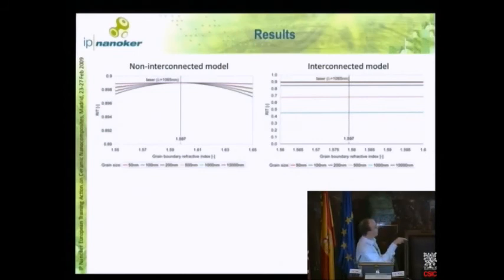So for different grain sizes, here we have the 10 micron grains, then the micron grain, the half micron, then we go down into the nanometer range. We can see that for whatever refractive index this grain boundary has, we get a quite dramatic reduction in the real energy transmittance as our grains get bigger. For 10 micron grains, it will be completely opaque. For the 1 micron grain, we get something translucent, whereas for nano-sized grains, we get something which is transparent.